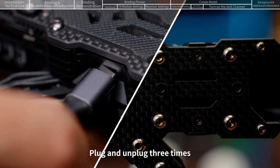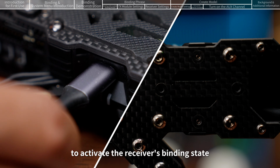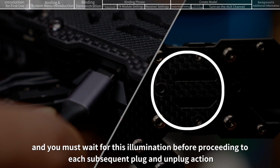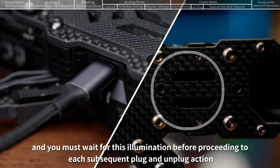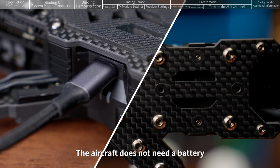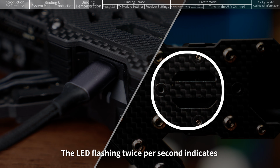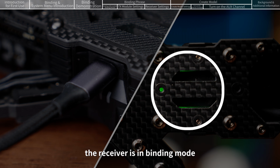Plug and unplug 3 times to activate the receiver's binding state. Note that the status LED confirms valid power, and you must wait for this illumination before proceeding to each subsequent plug and unplug action. The aircraft does not need a battery. Once all 3 cycles are complete, the LED flashing twice per second indicates the receiver is in binding mode.